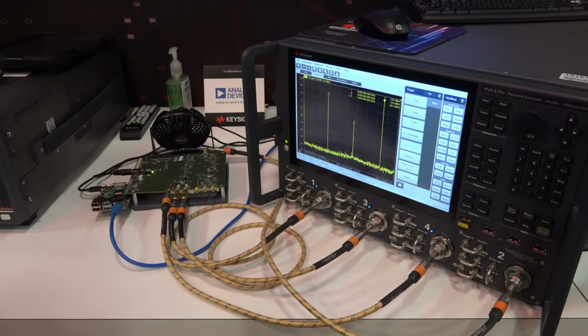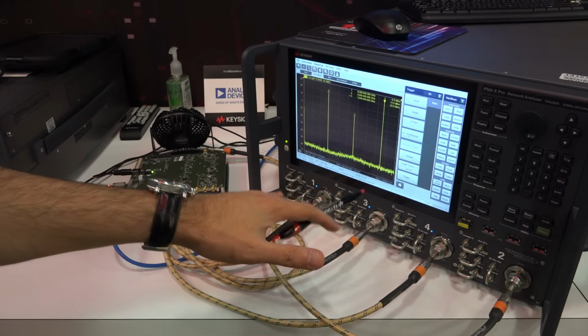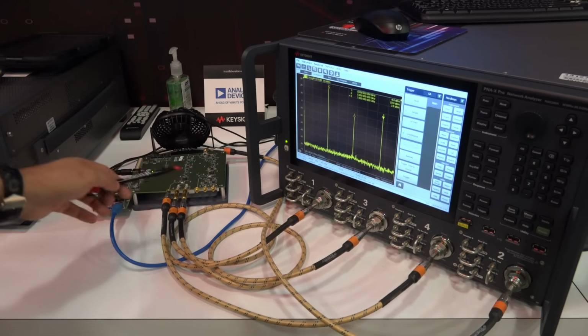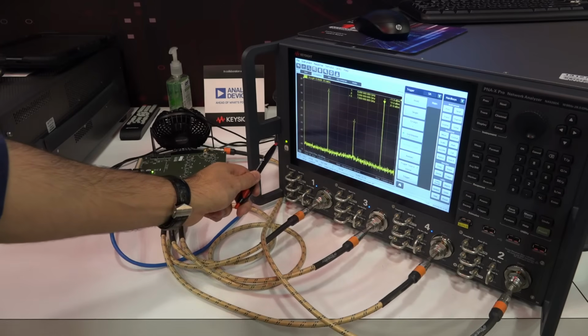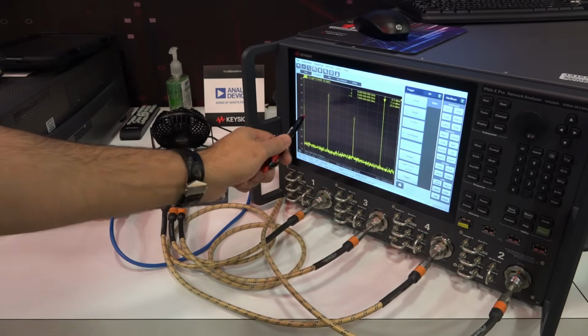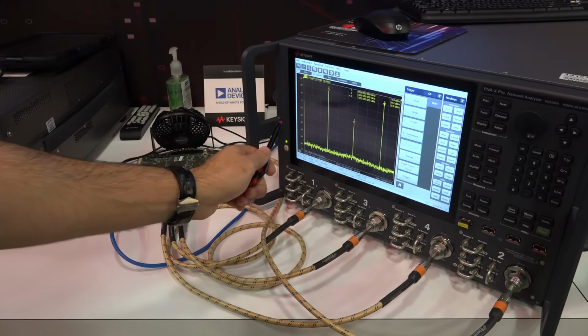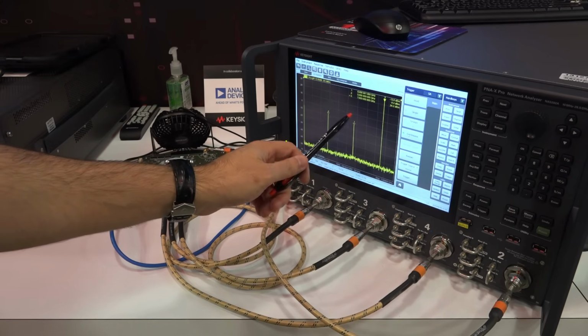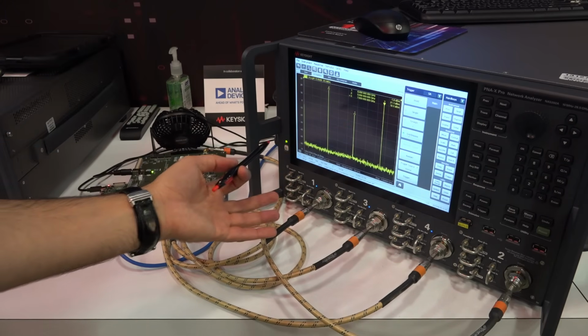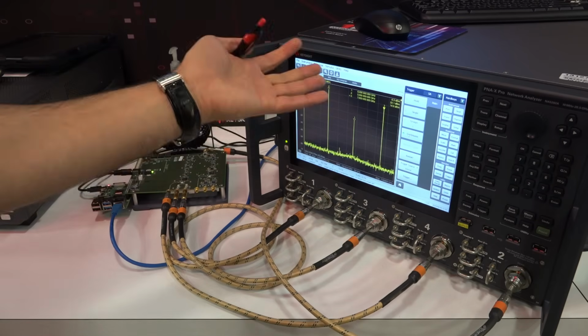So here's a quick live demo running the PNX Pro connected to an IQ mixer. You can see here on the x-axis, we are sweeping the phase. And of course, as you sweep the phase with the two independent sources, you see the upper and the lower sideband, the image, go back and forth between the two of them. A very unusual measurement to see on a network analyzer, because you're looking at spectrum.